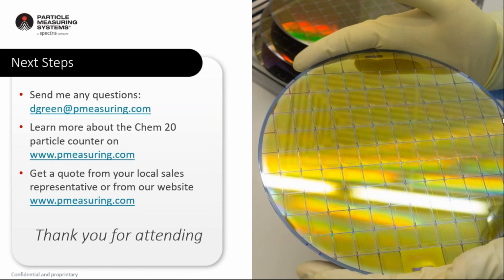And so that might be causing the chemical being filled into one of the other process tools to be contaminated. So those would be the three primary places that I would think most people would monitor, and then they would use the other places to look for contamination if there is a problem in the other locations. Okay, that makes sense.